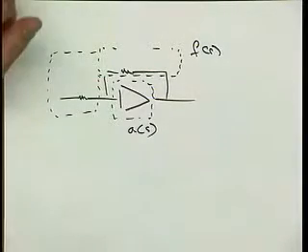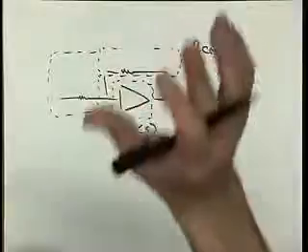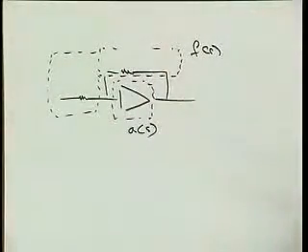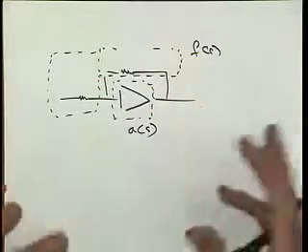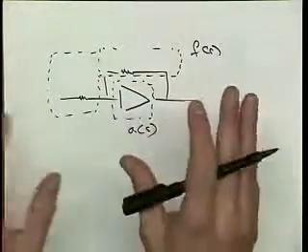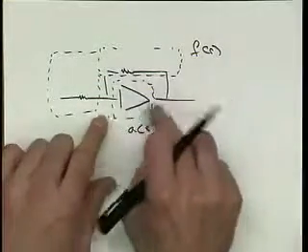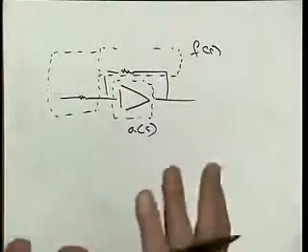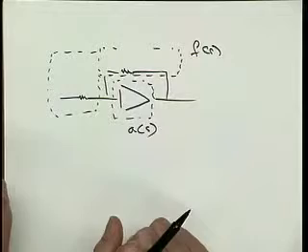There is another thing, but now the minute you use a transconductor here, then the story is different, right? The loading really matters, and then you try to simulate the loading by hanging, for example, these 2 resistors in series here at the output to simulate what their effect would be.